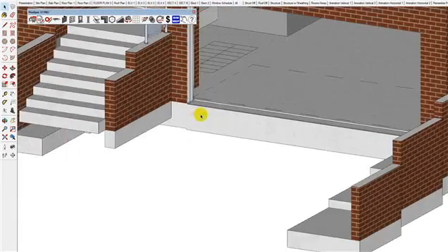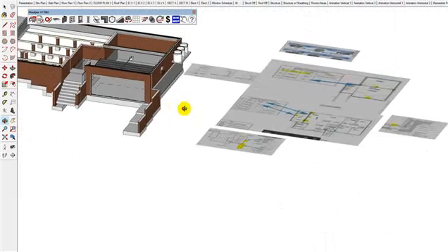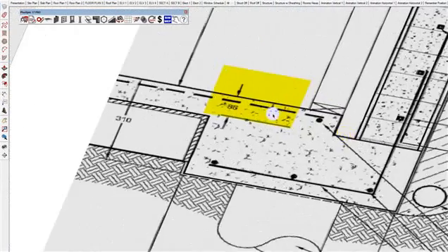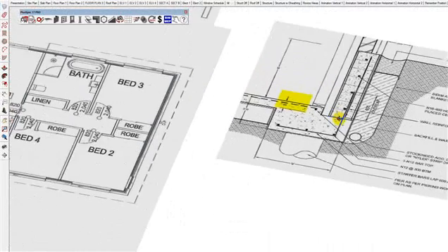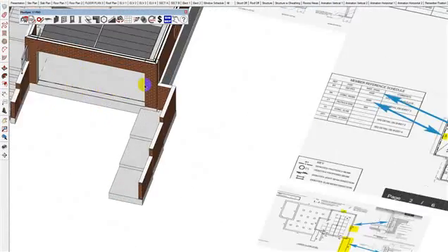Now, another thing that I've only just noticed is that your slab's supposed to have a step down. If you look at this here, it says you've got an 86mm step down on the slab and a 310 overall footing. Let's have a look at what you did.